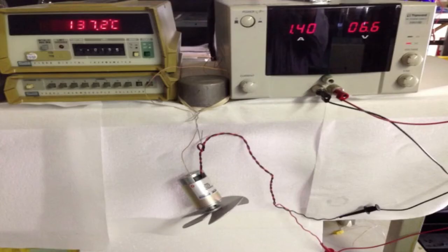Heat is generated inside the motor primarily by resistance to current in the windings. The test is stabilized when the maximum winding temperature, 150°C, is reached. Additional heat is conducted through the connection contact between the motor shaft and coupling. In this case, a fan blade assembly has been set screwed to the shaft. You can see this reduced internal winding temperature by 12.8°C.